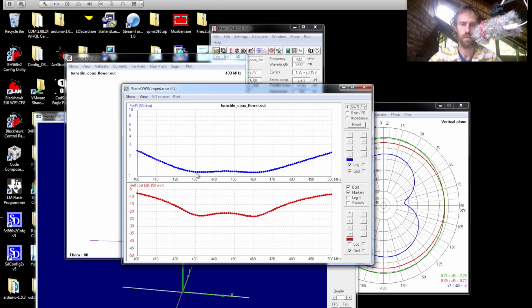In this case, lots more leeway above than below, but because of this wideband characteristic, you can be a little bit more inaccurate with your measurements as well. But it's not a problem to be down to a millimeter anyway. The values that I've got on my actual cheat sheet here are accurate to a millimeter, which is more than enough. 2 millimeters is fine.